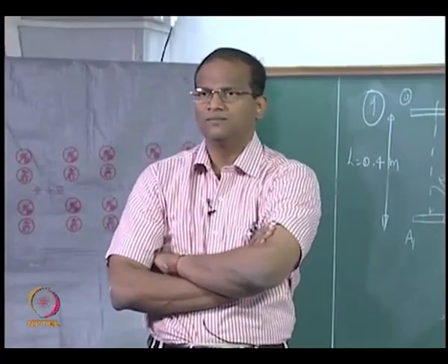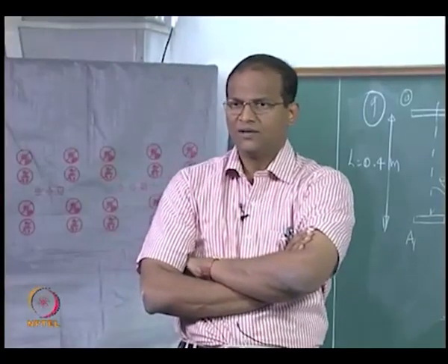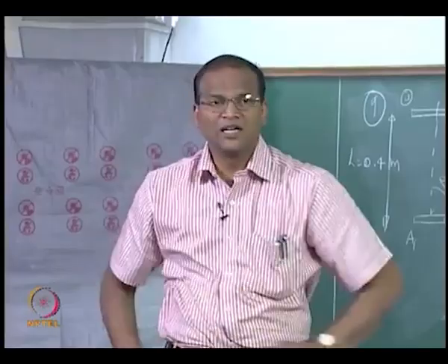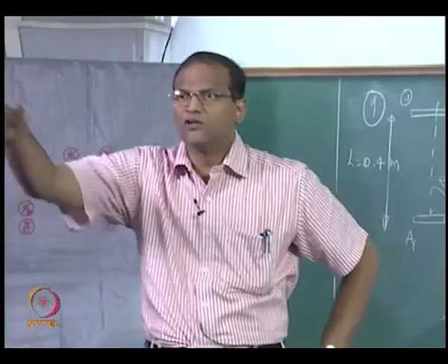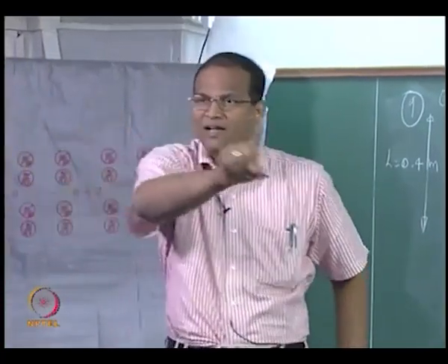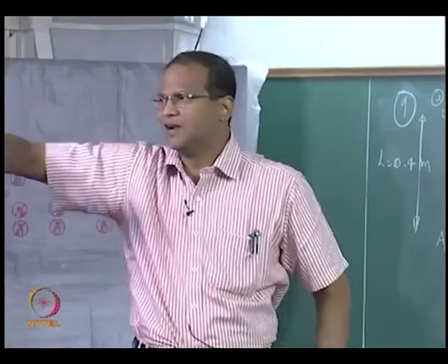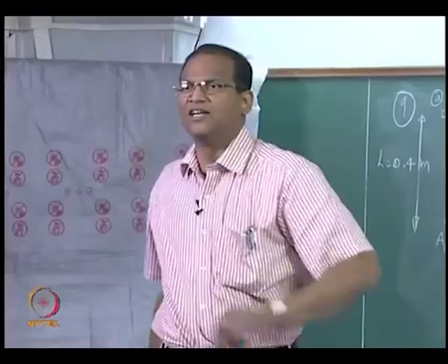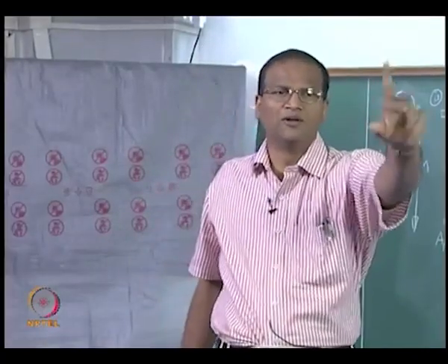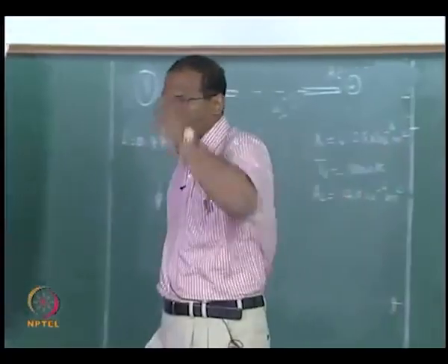You must use Stefan's law, you must use the concept of solid angle. Originally, when I started out with solid angle, I gave you the emissive power. Now we have gone through 10 or 12 hours of this course, so I will give you the temperature and you have to multiply it by the emissivity. Using solid angle, on the right hand side you will get an expression with only one unknown, epsilon dash of theta. On the left hand side you know the power the detector is measuring. Solve for that one unknown, epsilon dash theta at theta equal to 0. Please do the first part; the second part will automatically flow, but the radius will change now, correct?